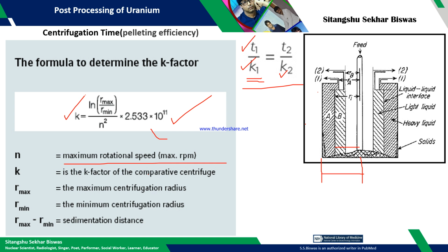Then the bearing design: it's a very difficult task to select the dynamic capacity and the material. It will be very difficult to design. Again, it goes to material science. Then the construction of the rotor, its machining, the tolerance, the dynamic balancing.